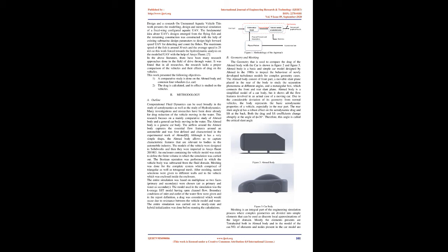Mortaza and Barsos et al. presented a study on underwater vehicles for drag reduction by means of hydrophobic surfaces. To reach an efficient underwater vehicle, a novel approach is introduced in this article to reduce the drag of underwater hulls. Total, friction, and pressure volumetric drag coefficients for the L20 profile, as a function of the sliding coefficient. Variations of the slip velocity on the wall for various values of the sliding coefficient.